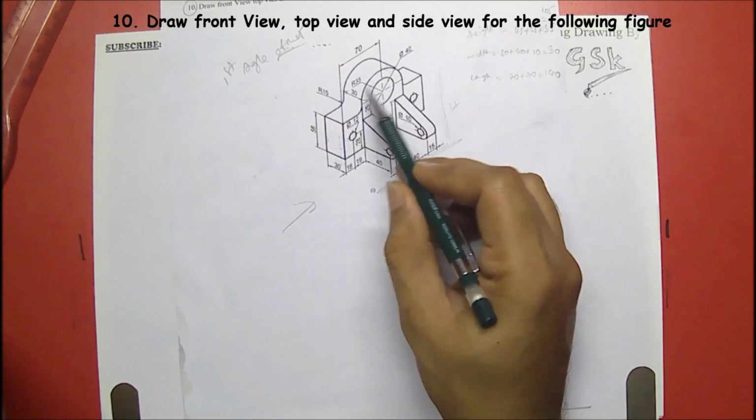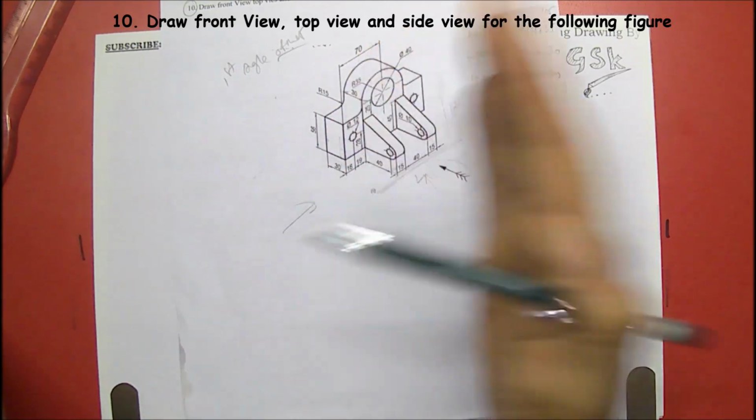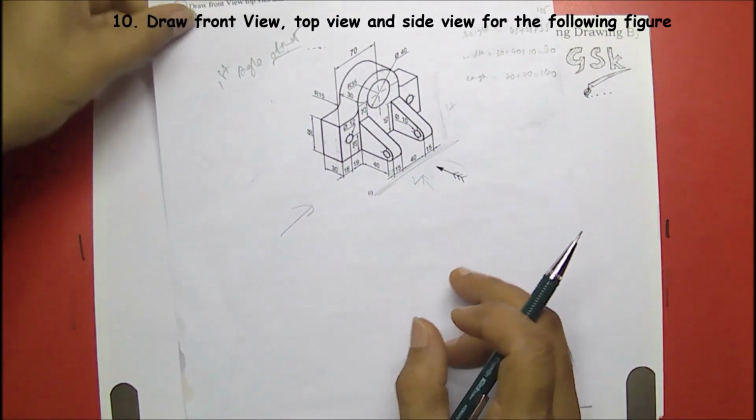So the front view would be coming above the XY line and the top view below XY, and your left side view would be falling on the right side of the drawing sheet or reference line. So let's start the problem.